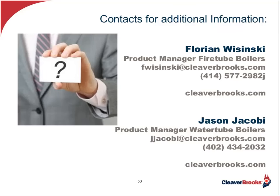This is Earl Pepcorn. Just a couple of comments here. The steam traps have always been a subject of discussion because they require maintenance, properly maintained to keep your steam system functioning properly. But what we have basically seen from the heating application, especially in the northern climates, is a condensing hot water system runs much more efficient than a steam heating system.